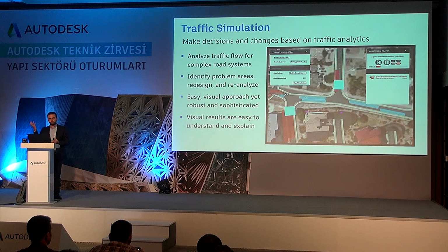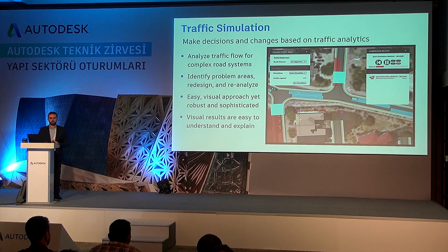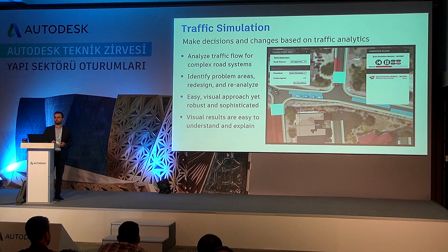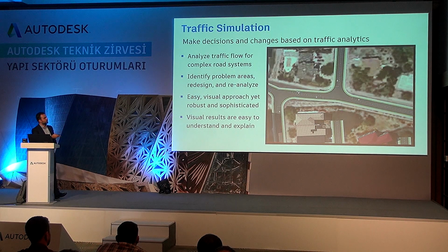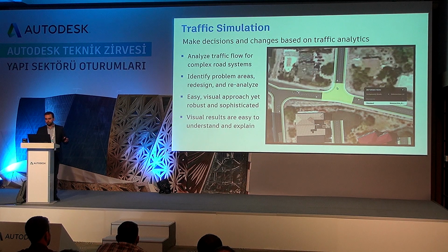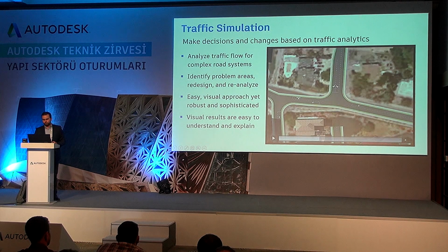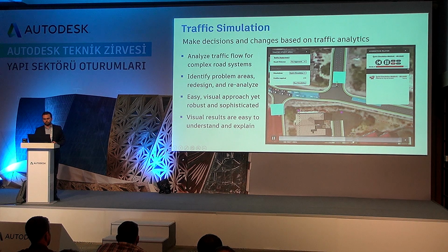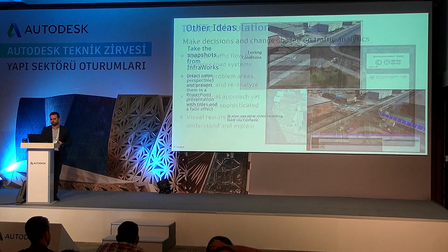Inside of InfraWorks, that same model that we've created, we can bring the model into InfraWorks and do simulation of the traffic. And by the way, this is almost free of charge. Instead of our customers having Vissim or the other tools which cost a lot of money, this is almost free. It takes like a couple of cloud credits, a few dollars, to do all the simulation and analysis and show you that if you need, for example, to add one additional lane, how would that affect the level of service inside of the InfraWorks platform. So also, we're moving from capturing the data, designing the road, and then into construction.